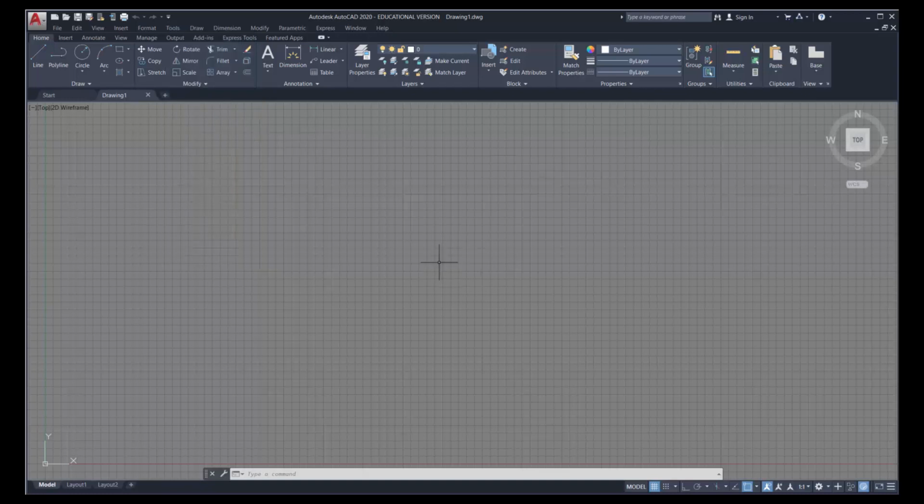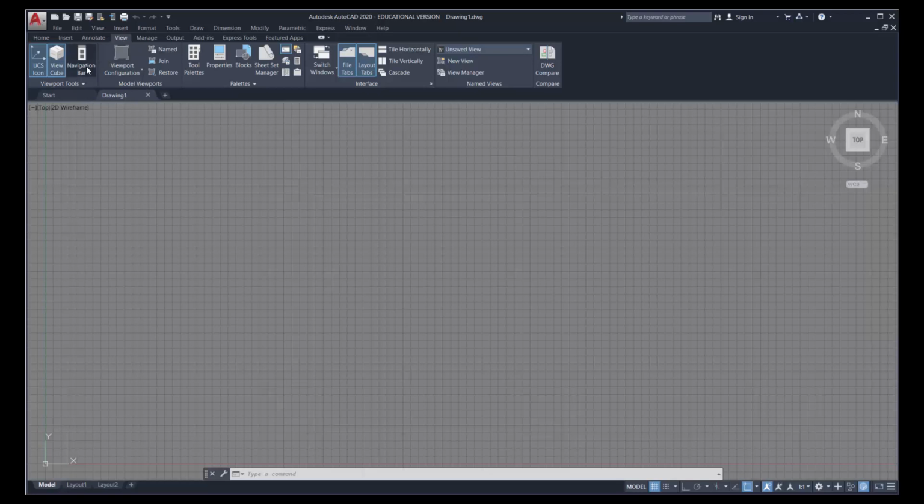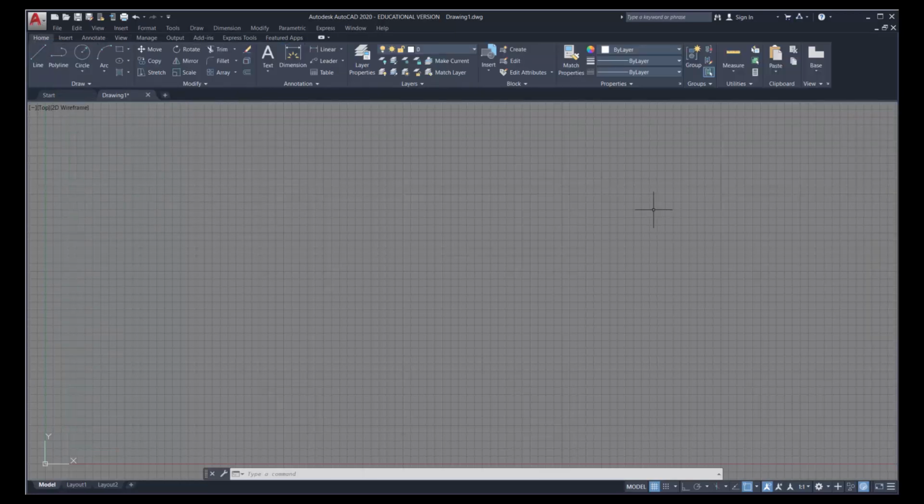Now, for the purposes of this project, we're going to remove this icon in the upper right-hand corner. It refers to isometric as well as 3-dimensional drawings, and so I don't want anybody accidentally touching that. Their screen will go out of whack, and sometimes that gets confusing. So in order to do that, in the first row of text menus, you see the word View. Just click on that. And the icon that's highlighted that says View Cube, just click on that, and it'll remove that cube. And then select the Home menu once again. And now we're ready to begin the drawing.